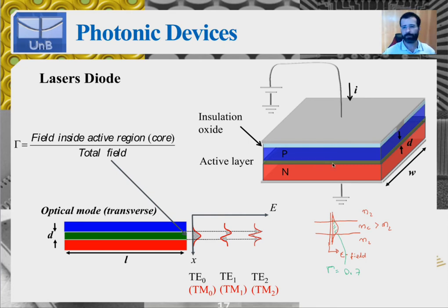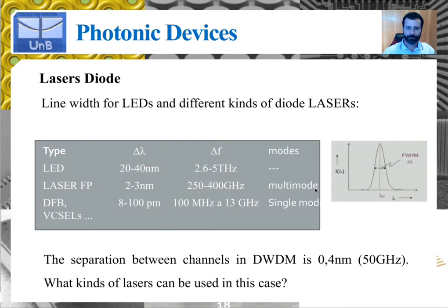To see this, you can compare this length to the wavelength of light, which is of the order of say 0.5 micrometers for visible light, and 1.5 micrometers for infrared. So around 1 micron is much smaller than 500 microns, right? And that's why the cavity is considered to be large. No doubt it will be a multi-mode cavity. So multi-mode for Fabry-Perot lasers.